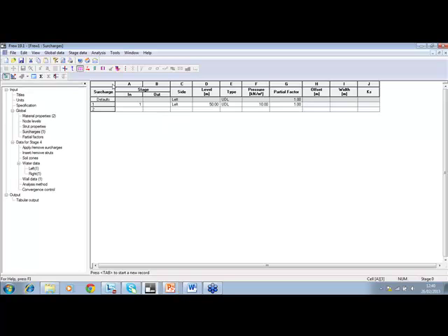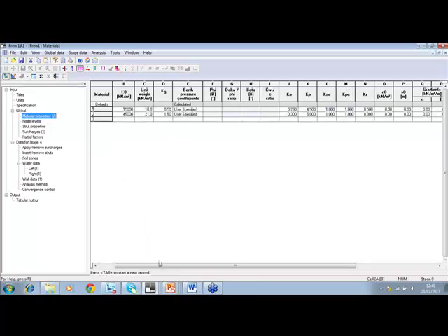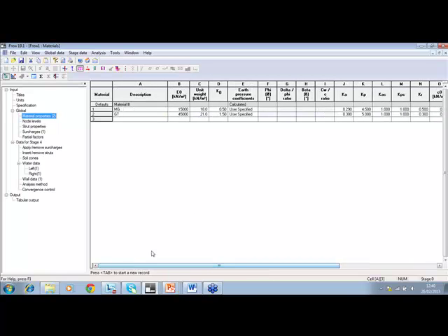Now for the surcharge feature, this isn't necessary. It was just a little bit to show you how it's done. But during a lot of large projects, what I have done is I have made, for example, a materials table, and in Excel I have saved the material properties for a number of standard materials. And then every time I set up a new Frew file, I just copy and paste it in instead of having to type it in every time. So these shortcuts are useful, especially when you're working on bigger files. So we've inputted the surcharges.